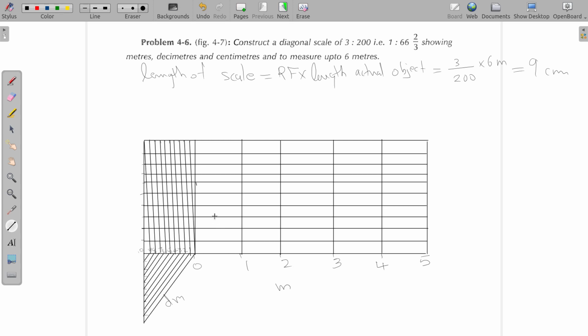Alright, now we can divide each of the small sections into 10 equal parts using this vertical line. How is it possible? This division here corresponds to this division, and the line starting from the 0th division and ending at the first division has been cut into 10 equal divisions in the almost vertical line, and we can use this horizontal distance as smaller accurate distances.